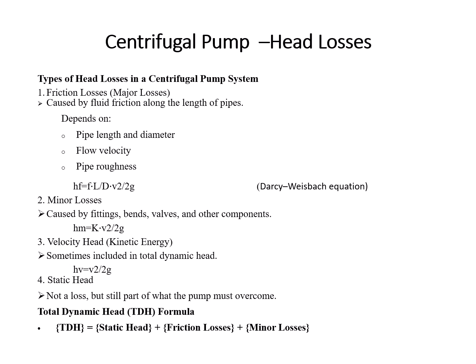In any system using a centrifugal pump, the total energy, which is the head, the pump must overcome is more than just lifting water vertically. It also includes losses due to friction and fittings in the piping network. And as you can see here, types of head losses in centrifugal pumps.